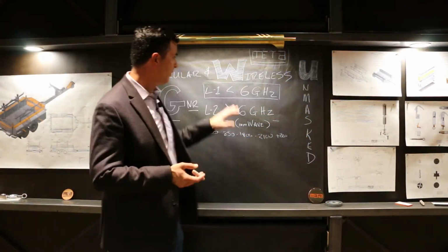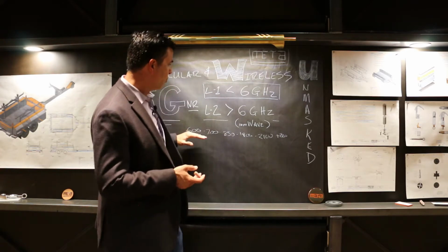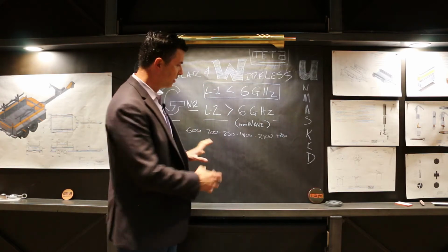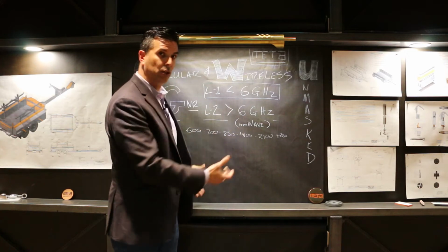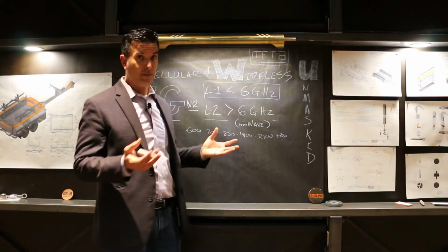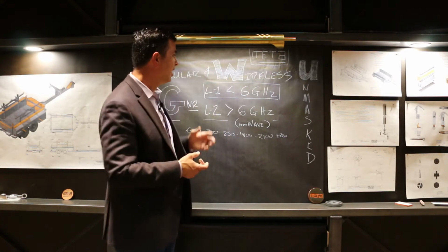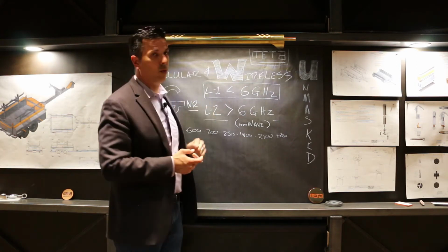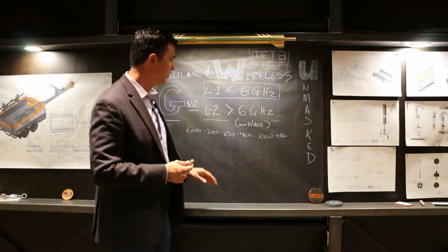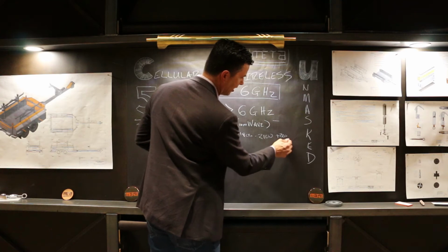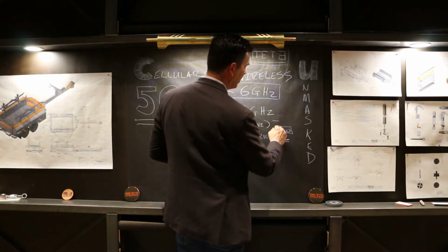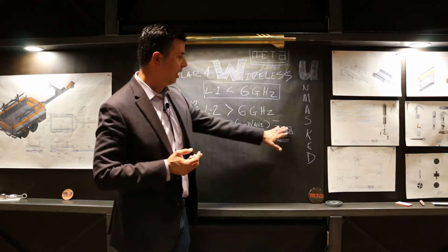So really what you see with the level 1 5G is repurposing of the existing cellular bands that we use today. In some cases, they'll do carrier aggregation, they'll make it into a larger channel. There's some expanded 2100 bands they use. The CBRS band of 3.5, that's kind of a private LTE. You've got a lot of different options in the L1 type of 5G, using the existing frequency bands. Now T-Mobile, right now, they have a lot of frequencies in the 2500 band. Okay, 2.5 gig, 2.6 gigahertz. They have a lot of bandwidth.